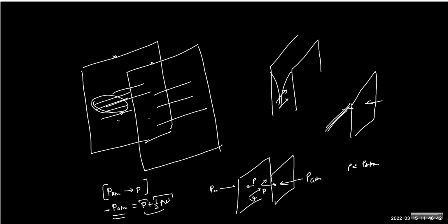So the higher the blow or the higher the velocity, the more the drop, or the lesser the pressure, and therefore the papers will come closer to each other. So the loss of one kind of pressure is compensated by the other kind of pressure. Loss of static is compensated by the gain in kinetic pressure. So that is how we think about it. The Bernoulli equation is common sense. You can think this way: if one pressure drops, the other must rise. Understood?